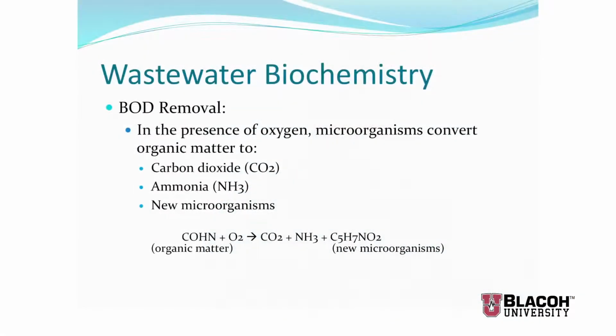Now, I said this was the biochemical equation for removing BOD. Where's the BOD in this equation? Well, remember, BOD stands for biochemical oxygen demand, meaning it's the oxygen that's absorbed in the biodegradation of this organic matter. So in a sense, it represents the organic matter. It's a surrogate for actually trying to measure all of these different organic chemicals and their concentrations.